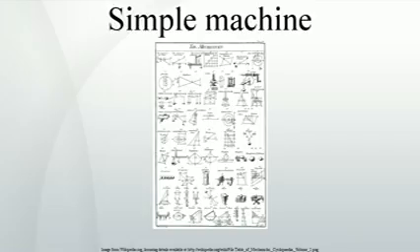He realized that a lever, pulley, and wheel and axle are in essence the same device, a body rotating about a hinge. Similarly, an inclined plane, wedge, and screw are a block sliding on a flat surface. This realization shows that it is the joints, or the connections that provide movement, that are the primary elements of a machine. Starting with 4 types of joints, the revolute joint, sliding joint, cam joint and gear joint, and related connections such as cables and belts, it is possible to understand a machine as an assembly of solid parts that connect these joints.